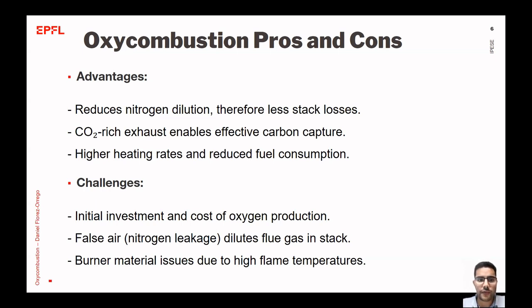It may also suffer from false air leakage. In this case, the nitrogen that enters with air can dilute the flue stack gases, and in the worst case, it can even produce nitrogen oxides. And also, we have some burner material issues because of the higher flame temperatures.